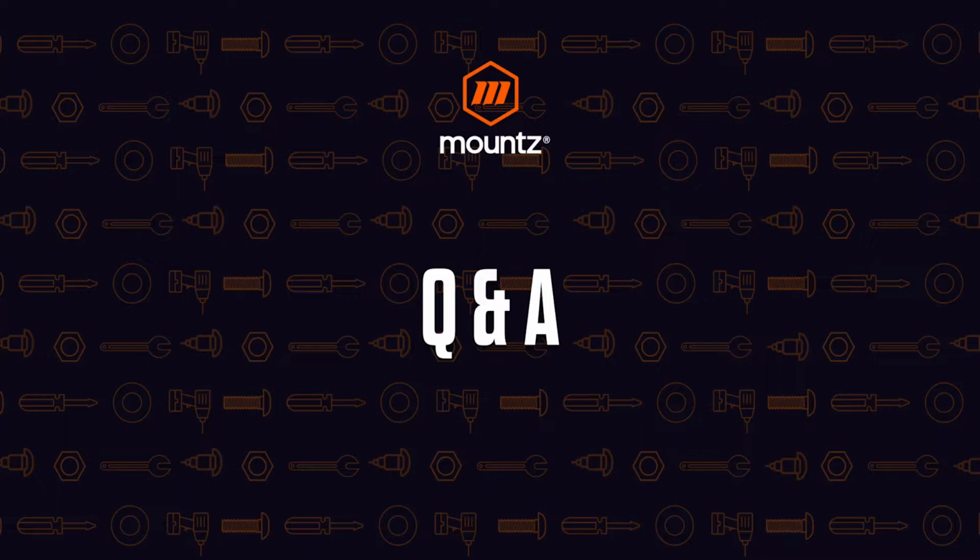And our last question is, when setting up the screw rundown time, do you recommend doing 10 or 20 test samples first? So typically, you want to do as many as you can in the same type of environment that the actual rundowns will take place. That's going to give you a better sample size to be able to gather the basically self-learning portion of the rundown.